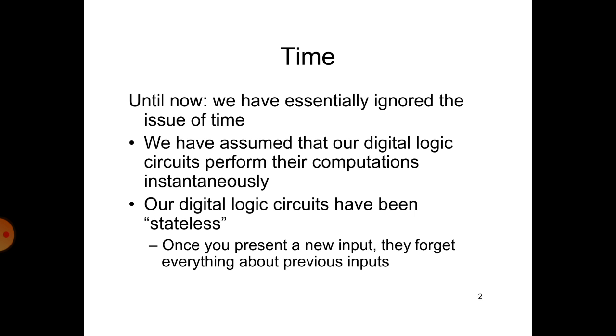Until now we have essentially ignored the issue of time. We have assumed that our digital logic circuits perform their computation instantaneously. So our digital logic circuits have been stateless. Once you present a new input, they forget everything about the previous input.